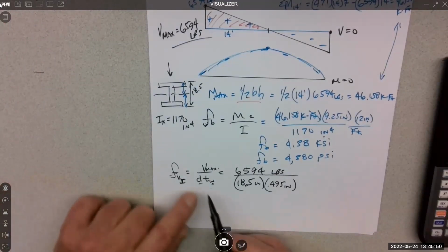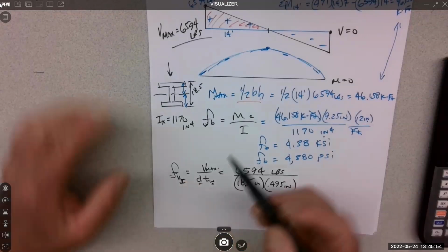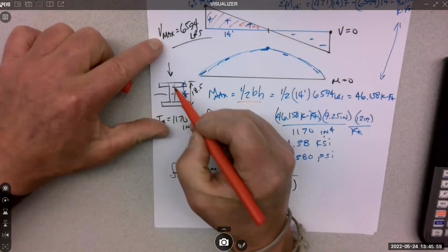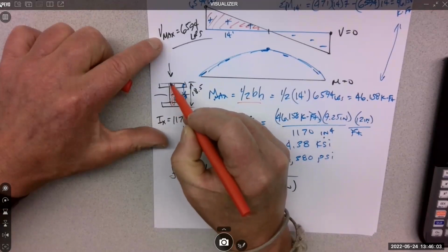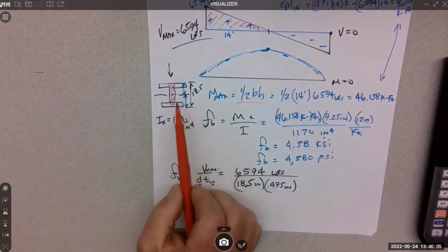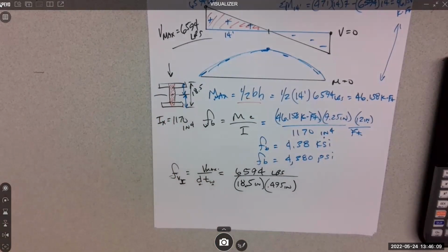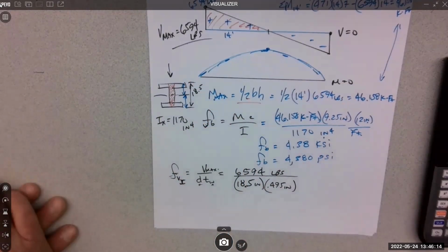It's actually full distance, D. So it's here, I'll show you. It's this area, right? It's that middle rib, full length. That's what's doing all of the resistance in the shear. These flanges, hardly doing a thing.